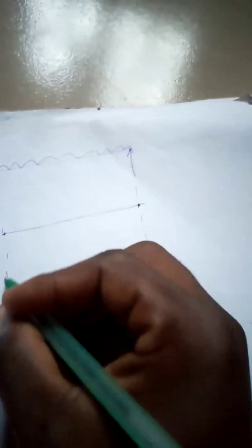we have your uniformly distributed load. For our shear, now if we check for our shear, you can see at x we have WL over 2, at L we have minus WL over 2. So at x we have WL over 2, here we have minus WL over 2, and then at the midpoint, which is L over 2, we have 0. So it's going to look like this.